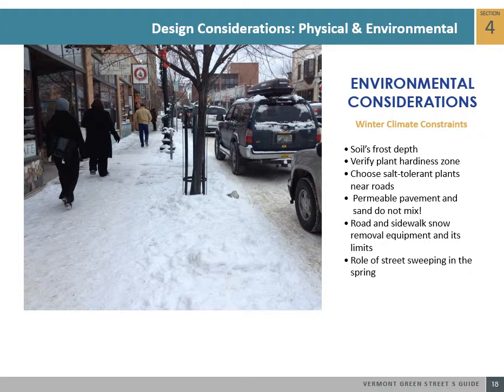Plan for street sweeping soon after the snow melt in the spring. Street sweeping will help reduce the volume of sediment that gets carried to conventional systems. Street sweeping can also be undertaken after intense storm events to prevent additional runoff from erosive material.